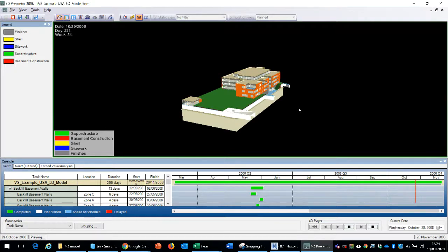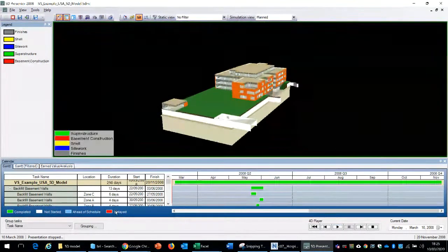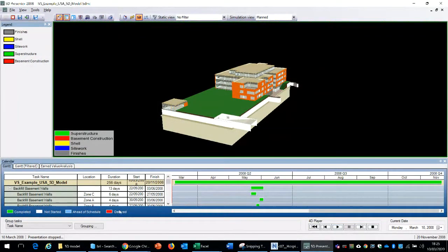We are seeing that these 4D models have been put into use for a number of different purposes. We can use it as an effective monitoring tool, so we could compare what was designed to what was planned. Here you can see a traffic color coding scheme is used towards the bottom. For instance, tasks that have been completed are indicated in green. Tasks that have been delayed are indicated in red. So you can have a visual interface telling you which of your tasks are going behind schedule.